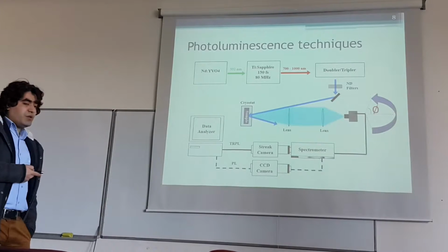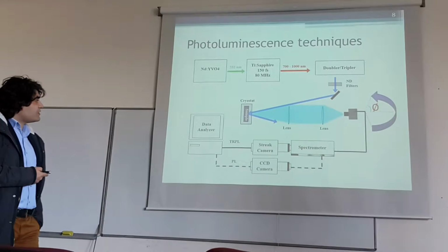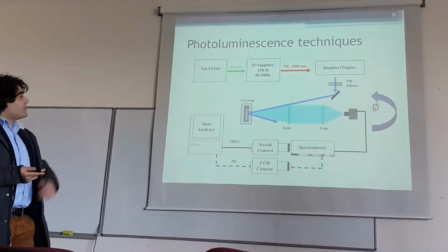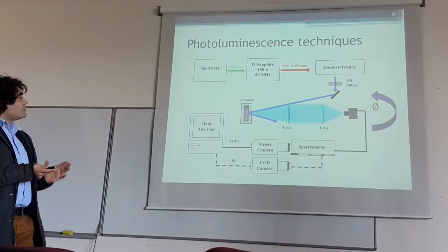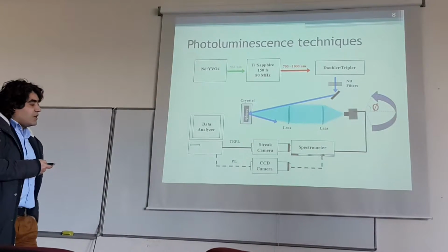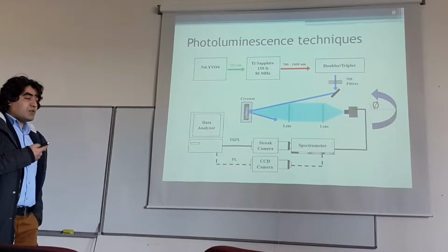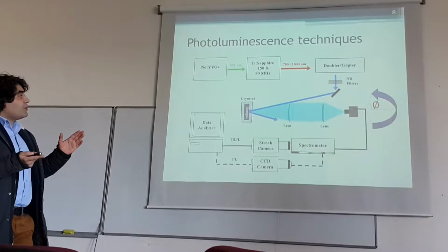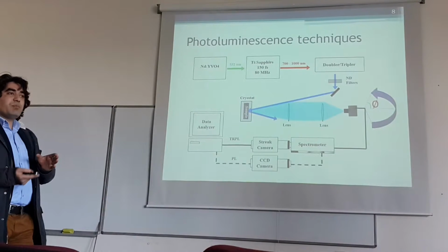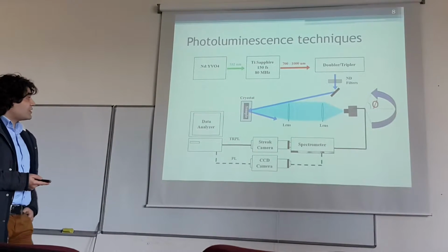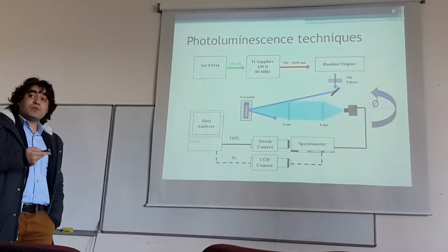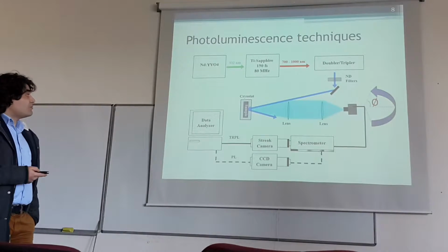We use 400 nanometer excitation because 15% indium quantum wells emit at 430 nanometer, so using this 400 nanometer laser, we will not excite the barriers or staircase injector layers. So our goal was to investigate only the quantum wells.